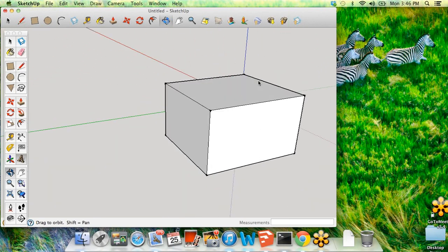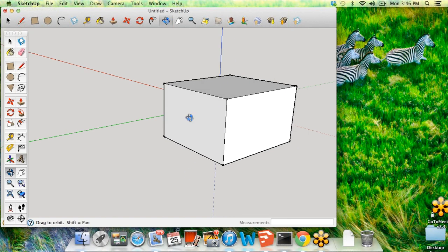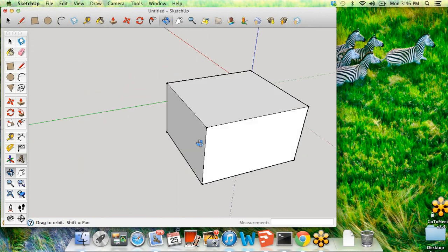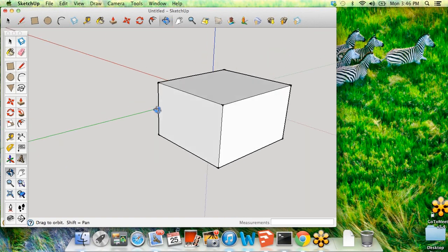If, for instance, we were making this box and we needed to use a specific material for this side, or you wanted to specify that this was side 1 as opposed to side 2 or 3, you can use text to show that. You'll find text in your large toolbar, and it has this ABC here, labeled text. Click anywhere on the screen and enter text will pop up, and you can type whatever you want. So I'm going to label this side as side 1. Just click.